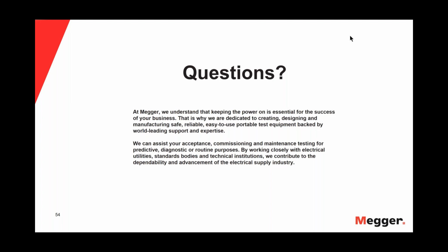All right, thank you, Henning. Marshall, what voltage level do you recommend for fault locating using the coincidence method? In which factors of operating voltage does this apply? Well, let me back into this question. If I understand it right, it's at what voltage level is our pinpointing device going to work? And if we back into this question, if we've done our breakdown test, then we know how much voltage we have to use for that particular fault to make it flash over.